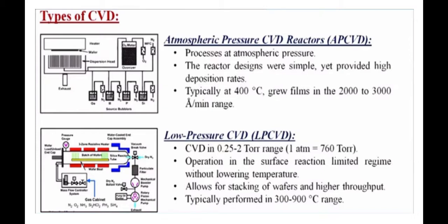Here the operation is in the surface reaction limited regime. Without lowering the temperature, it allows stacking of the wafers and higher throughput, and it is typically performed in the 300 to 900 degrees centigrade range. So here the temperature variation is a little bit bigger actually.